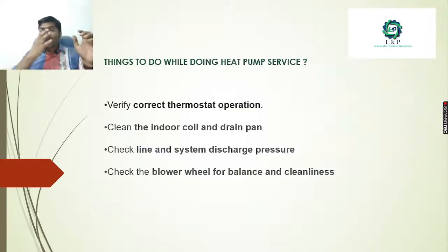And we need to check the thermostat operation, whether it is operating properly or not, and we need to clean the indoor unit and the drain pans also.